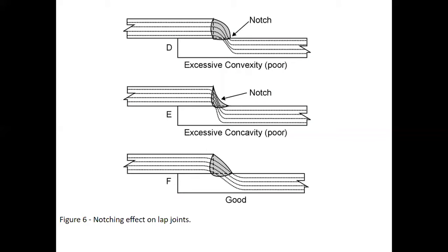So this is how some notches can affect, or your welding profile can affect your welds. We see these, we're practicing with some of these plates. When we get back, we're going to be doing a lot of these type of lap welds. So if we stack another one on top of here, it would just look like your stair set that we weld. When we're doing this, we do get stress flowing through here. Generally, you have both of these welded if you can. It's not often that you can always get back to the other side, but in our classroom, we're able to. So we're going to be welding on both of these.